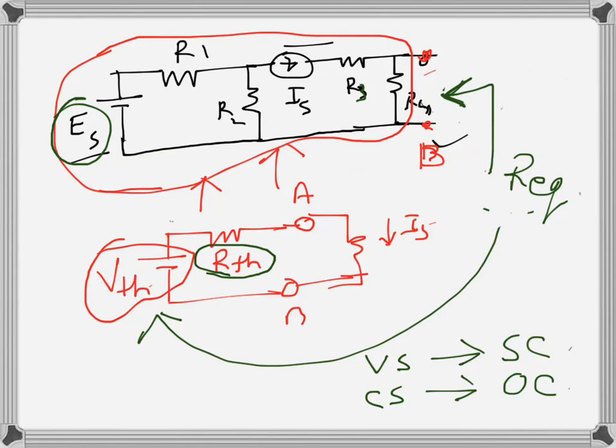And once we have the Thevenin equivalent circuit, we can just rejoin our desired branch, and we can calculate the voltage and current through it. It turns into a very simple series circuit, and then it is solvable. And since we are not interested in any other branch for this particular circuit, it actually becomes very simple by using Thevenin's theorem.